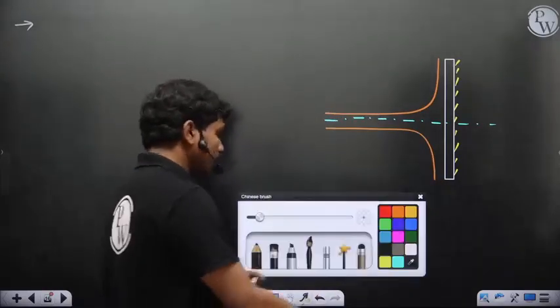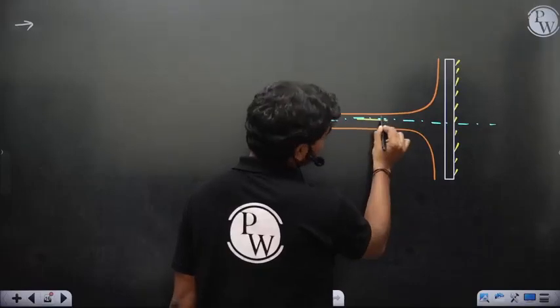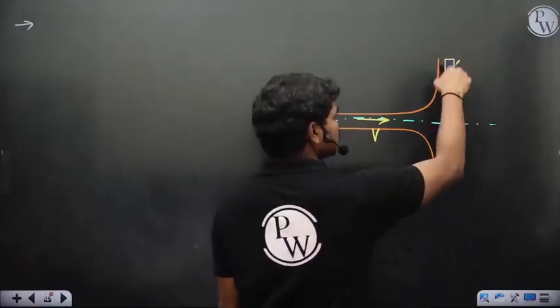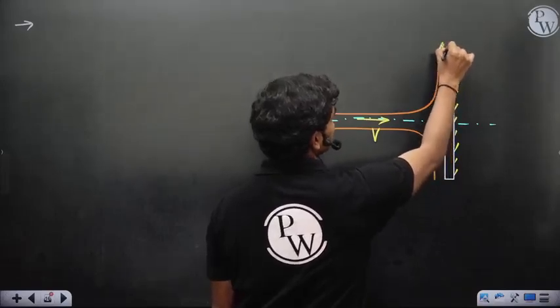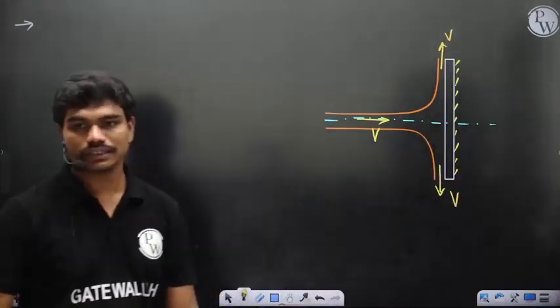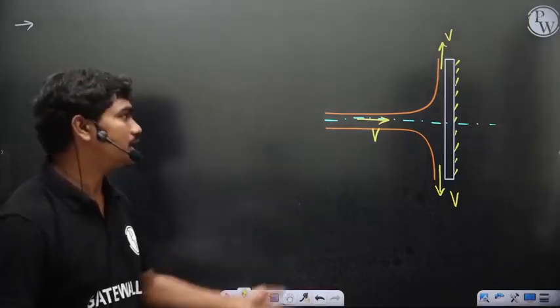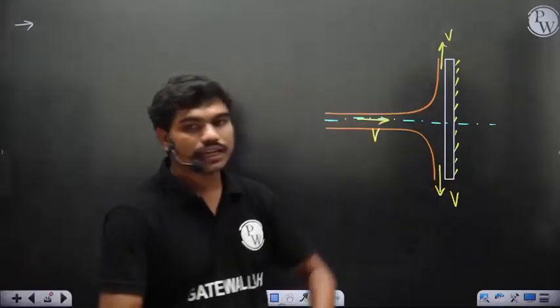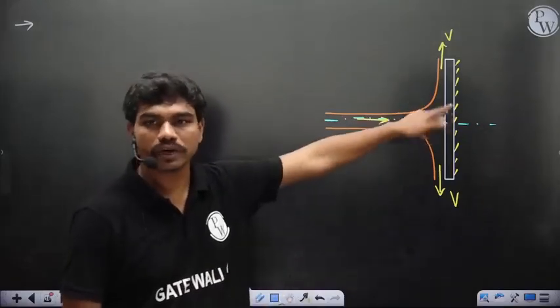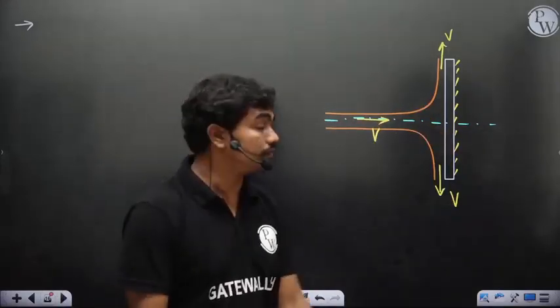Okay, fluid is going with a velocity v, then if there is no friction and nothing, there is no friction on the blade anything, the fluid just slightly smoothly slides with velocity v, of course, correct. This is what ideally happens. If there is no friction at these edges, then no energy is lost, this fluid will just go and come out. Everywhere pressure is open to atmosphere, so there is no pressure difference anywhere.